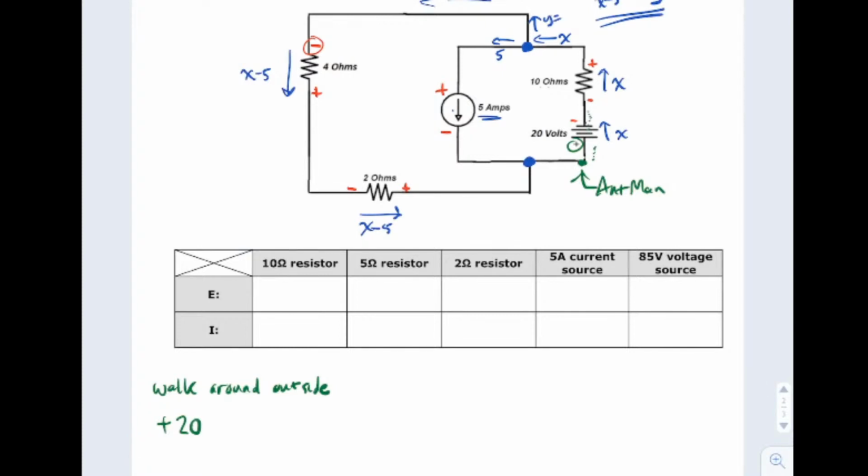He's coming into the next circuit element. He sees a minus on the way in. Put the minus there. I need the volts. Again, resistors. That's not volts. But if you multiply them, it's volts. So it's a minus 10x volts there. Ant-Man comes out. Well, he wants to take a corner and come around the outside, so he takes the corner.